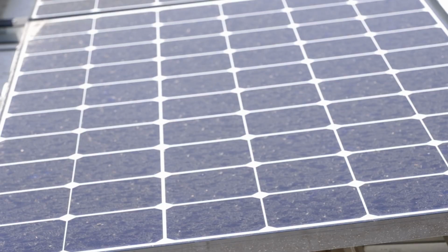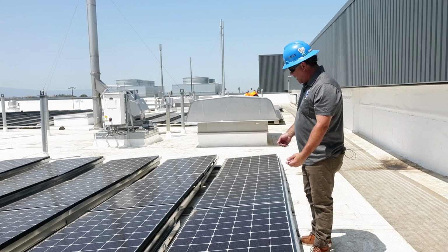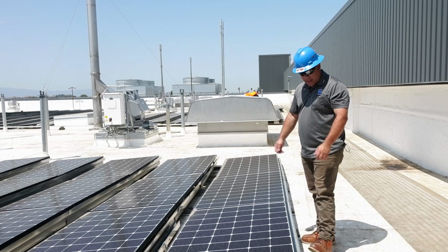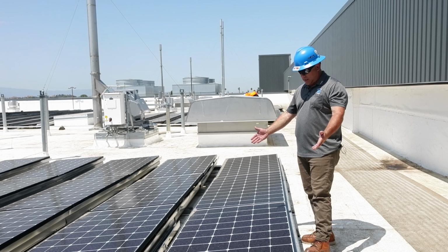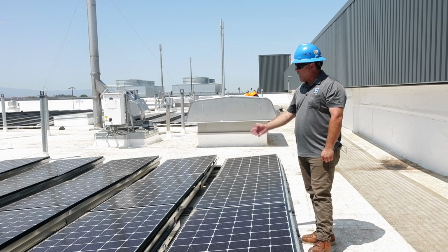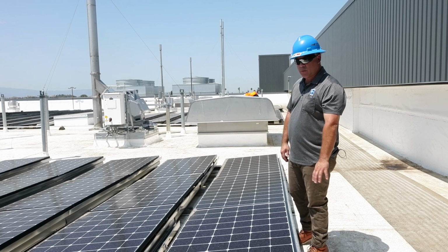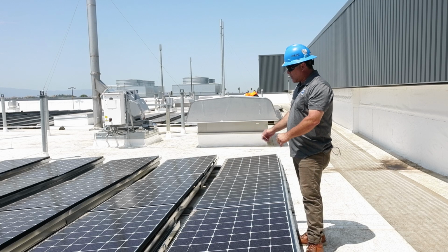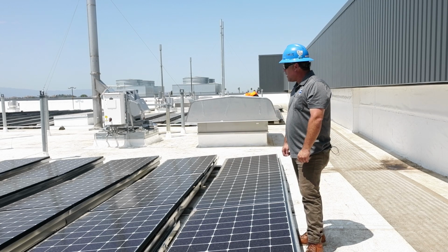The structure shouldn't be damaged unless something foreign hits it: a rock comes flying, a tree branch, somebody slides, somebody drops a tool. There's not much to talk about with these, not much we can do about them. If we have a broken string, we have to wait until nightfall just to avoid having any loads on the panels. Remember, as soon as they have light, these panels are producing. So there is potential, if we were to disconnect any of the wiring, that DC is going through it.